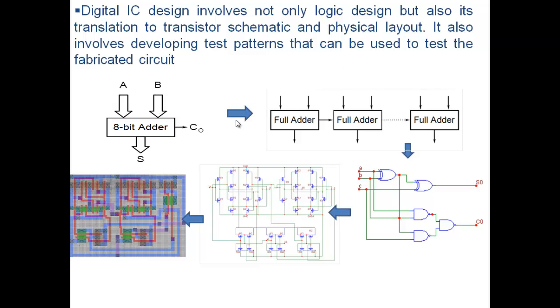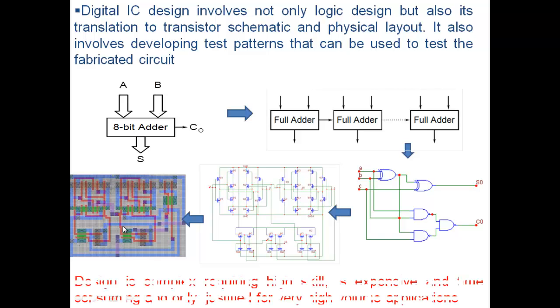And the transistor schematic has to be translated into physical layout. It also involves developing test patterns so that you can eventually test your IC, right? So digital design involves, of course, logic design, all this that you're familiar with, and also transistor schematic and doing the layout, okay?